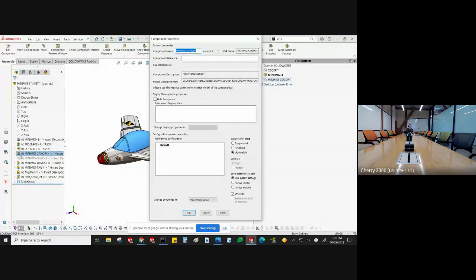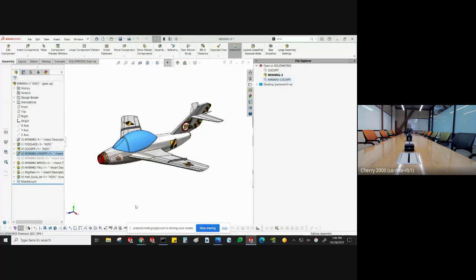You can change an assembly or a component or anything you want, and it's just this checkbox, envelope. So it's basically ignore in bill of materials plus ignore in mass properties. But it still takes the same amount of time to load up. It is a part file, it goes into your RAM. From that standpoint, there's not much difference.